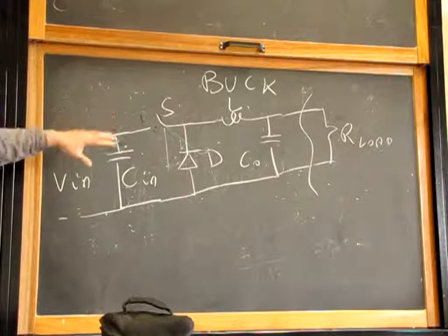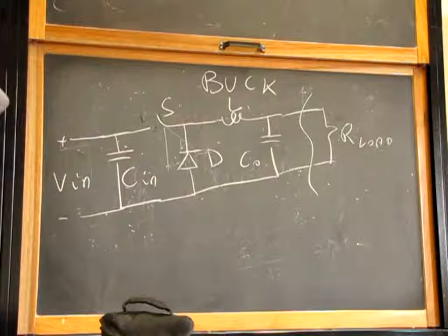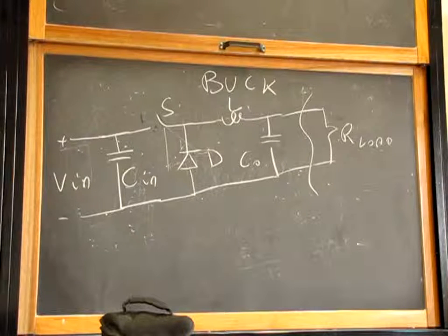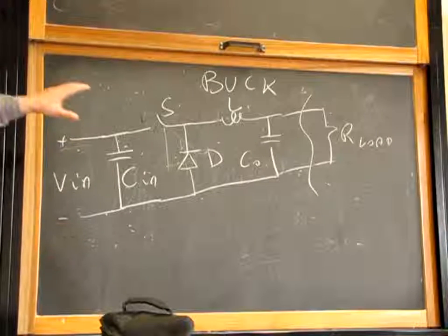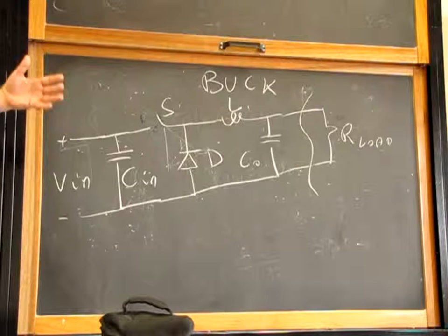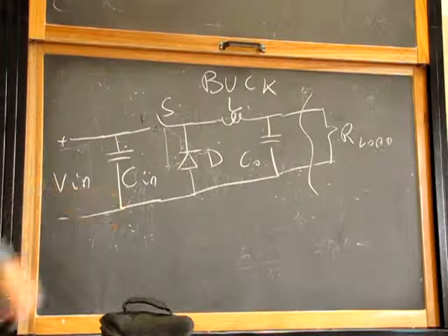There are thyristors used in buck converters, but those converters are far more complicated because they need an auxiliary circuit to switch it off. They were used on the old electrical locomotives, the first ones that had electronics on them. They had a buck converter type circuit with a thyristor, because the thyristor was the only power electronic switch, and an extra circuit to switch it off.